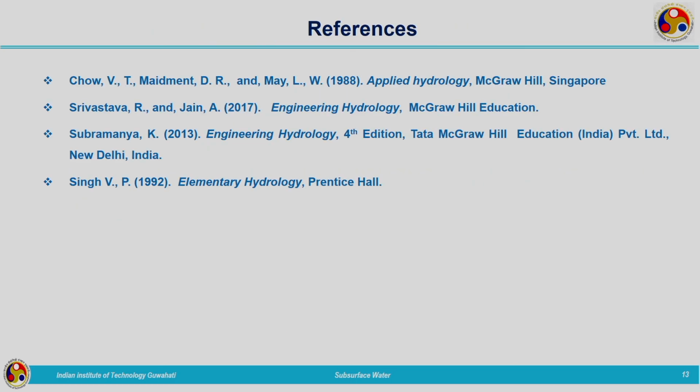So, when you are talking about the energy or head causing the flow within the unsaturated region, this expression should come to your mind. It consists of two components, that is, one is the datum head and the other is the suction head. So, how does the suction head come into the picture? It is due to the capillary action. And for more understanding of the topic, you can read through these textbooks.